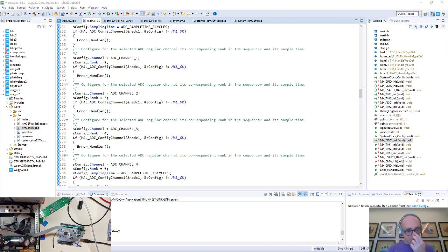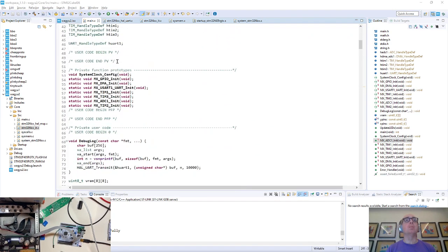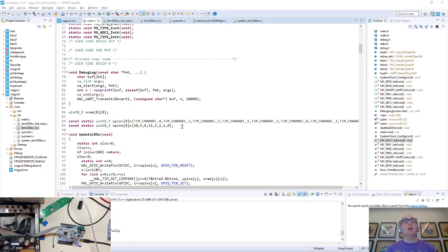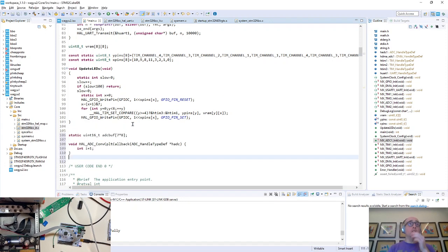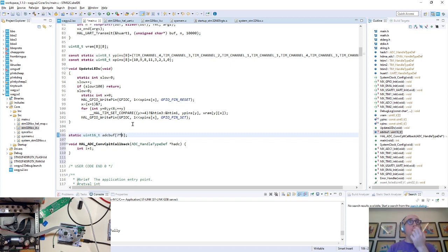So let me just consider what I want to do here. Go up to where we're dumping our code. That was the LED stuff. Right, so we're going to have a little buffer of 7 pins times 8 samples. I'm going to take 8 samples, which later on I could use to do smoothing or oversampling by hand in software. I'm going to take 16 bits at a time.